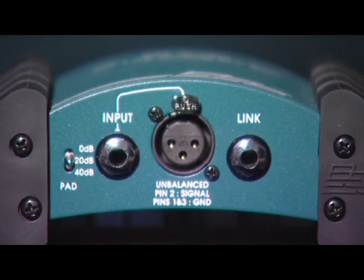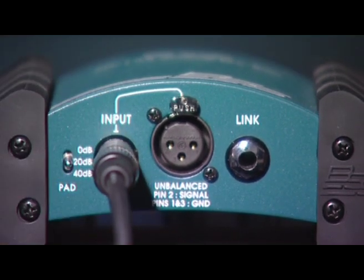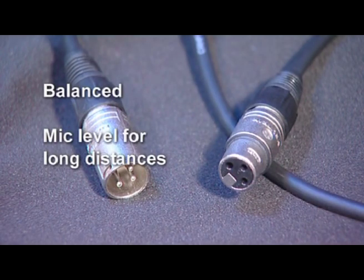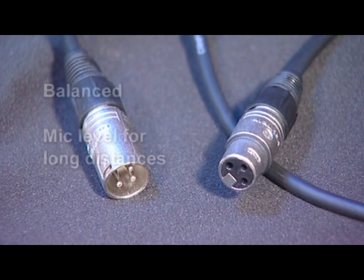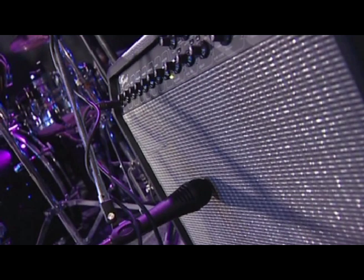A direct injection or DI box turns a low-level unbalanced signal, which might be from a guitar or bass, into a balanced one that can be plugged into XLR microphone inputs. Balanced signals can travel much further than unbalanced ones without losing out to noise and interference. Of course, you might want to just mic up a guitar amp for a more authentic sound.